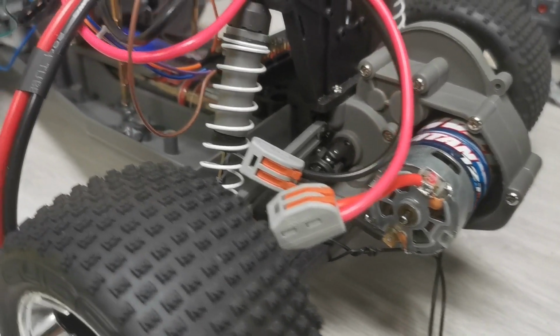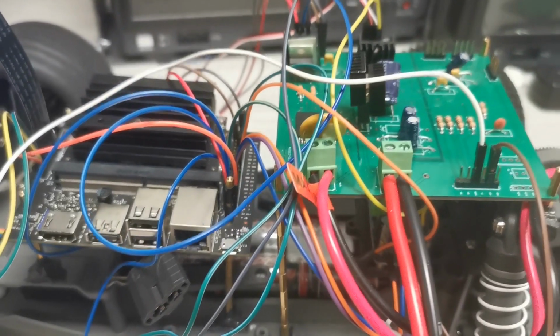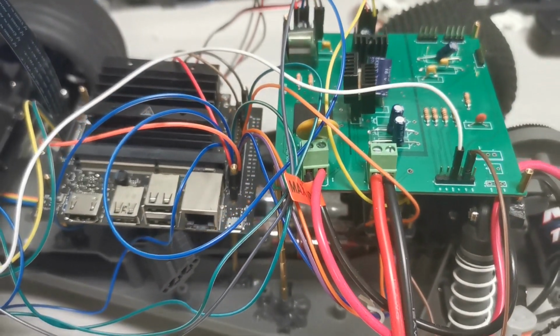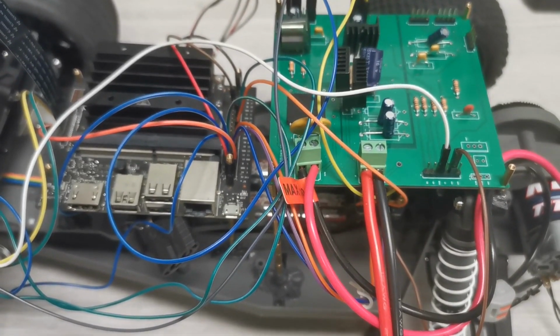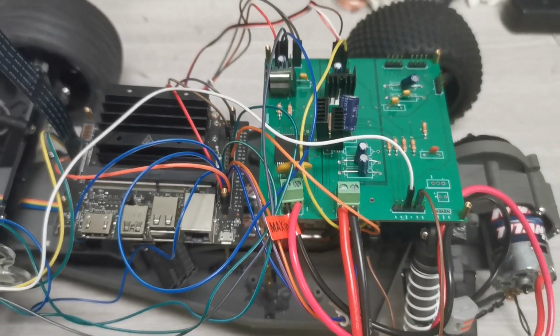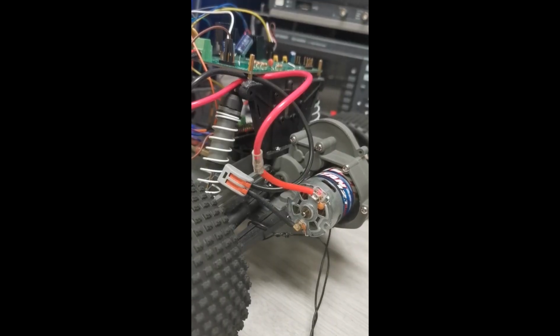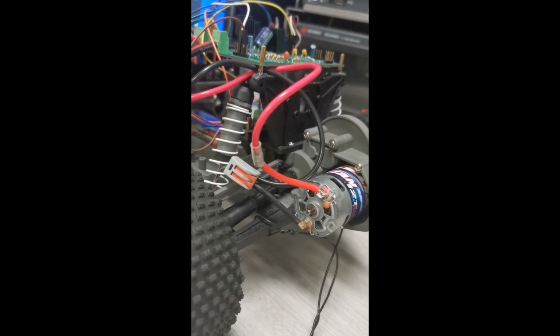For hardware, we can replace the current motor with a more efficient one to get more precise speed control. We can also improve the power efficiency by ensuring more effective power dissipation from the PCB board, and add an extra source like a power bank to supply power to the Jetson Nano and OpenMV to ensure enough power is supplied to the servo and motor. This will help us solve the PCB overheating problem, which improves the motor control.